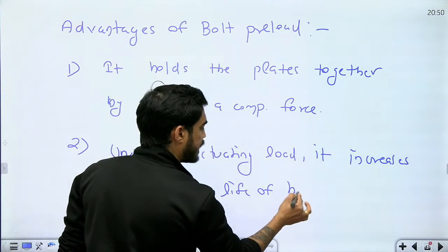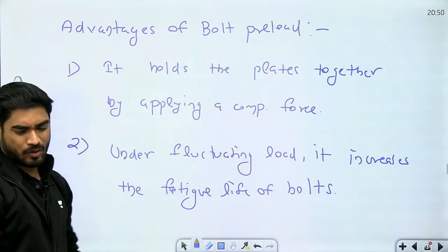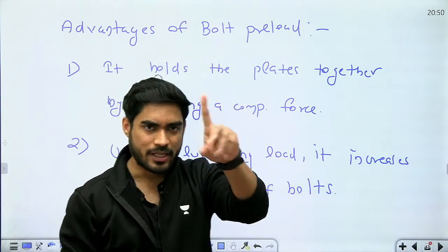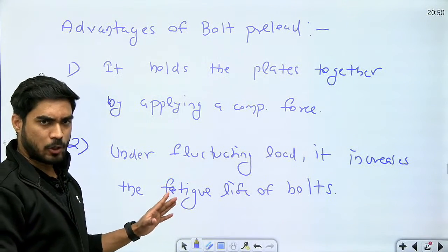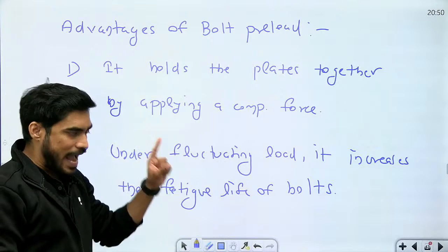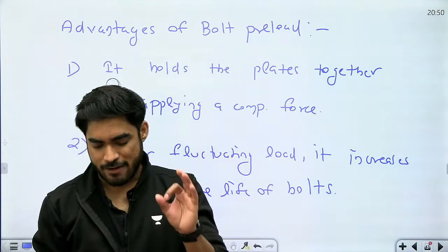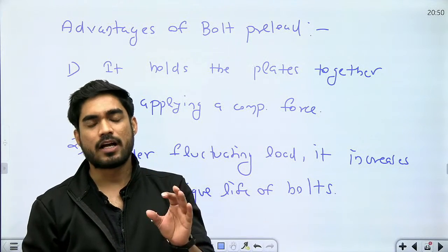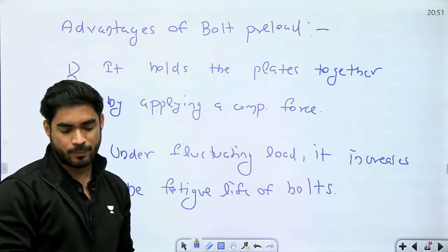Now beta, we will not discuss this point in detail. Okay, we will not discuss this point in detail because it will be a waste of time, but you need to understand that under fluctuating load, if you have bolt preload, then the fatigue life of bolt will increase.